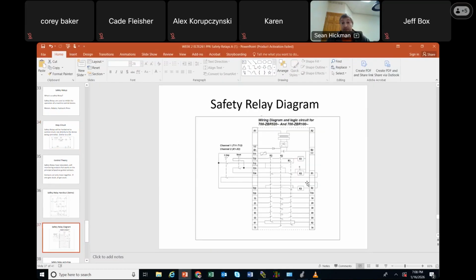Well, on this one, remember, who cares what's going on in here? You have to make these connections externally here in order for this relay to come on. But when it comes on, all that's happening is it's closing internal contacts that look like this, but you don't see them anyways, so don't get hung up on them, okay? So that's the safety relay.